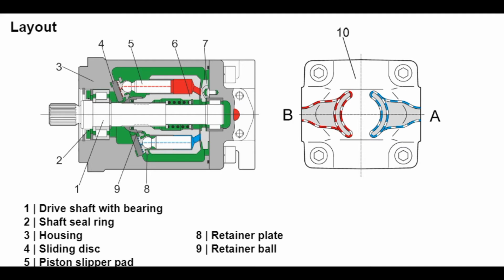Pressure on the piston causes it to pass down through the angled disc, sliding disc, and catch the cylinder 6. The cylinder rotates with the drive shaft, producing output torque. The forces at work in the hydraulic section of the rotary group, that is, the cylinder with pistons and control plate 7, are in equilibrium. The principle of the spherical control surface, its lubrication, the pre-charge pressure of the cylinder with springs, etc., is comparable to the function of the bent axis rotary group.